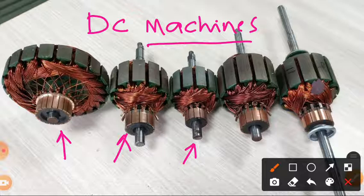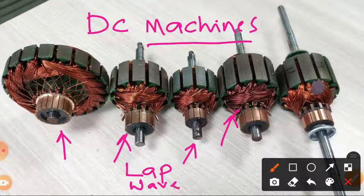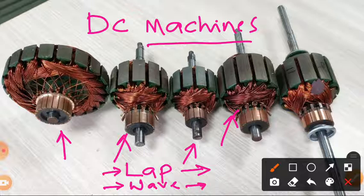The armature winding may be connected in two types. One is the lap winding, another is the wave winding. These two types of windings are generally encountered in our electrical field to run a DC machine. Regarding the lap winding, we have already seen in previous classes different types of lap windings, single layer and double layer, which we already developed. Now in this session we are going to cover the wave winding. Okay, so let us see that also.